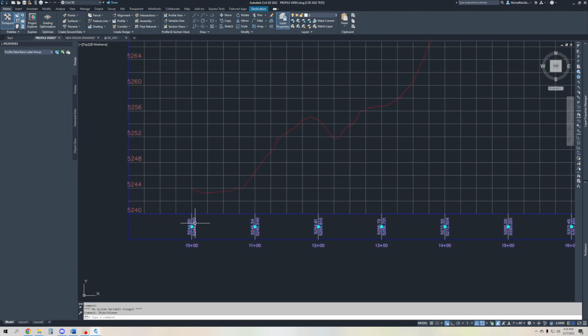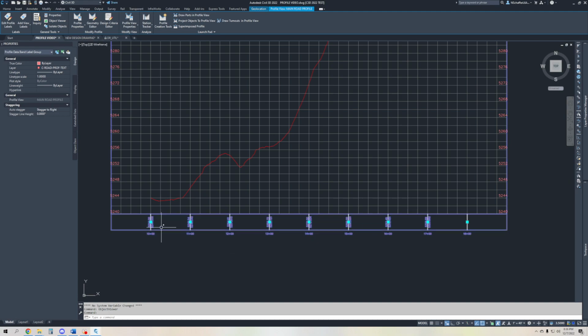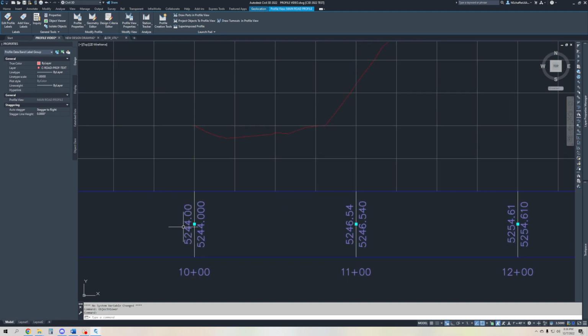So going back to what we were talking about earlier with our bands. This across here, all of these that are highlighted, these are going to be your bands, B-A-N-D, bands. So profile 1 is on the left side. Profile 2 is on the right side. How I have personally always been told it is shown, left side is your existing grade, which is this red line that we see here. Right side would be your finished grade, which is your proposed style.